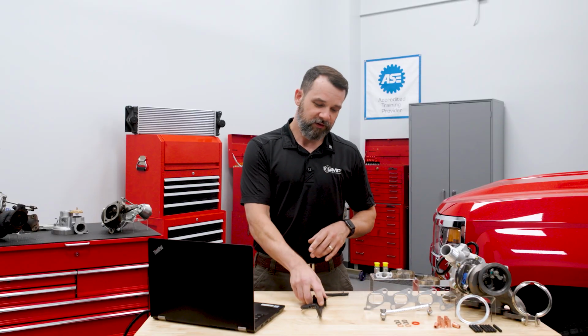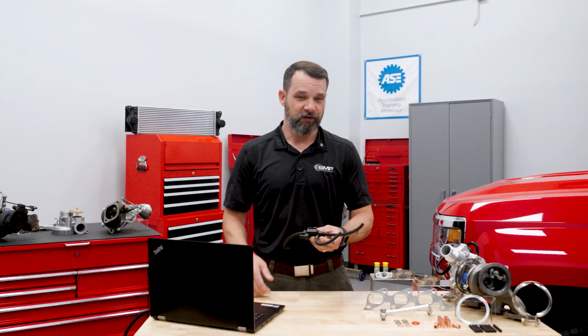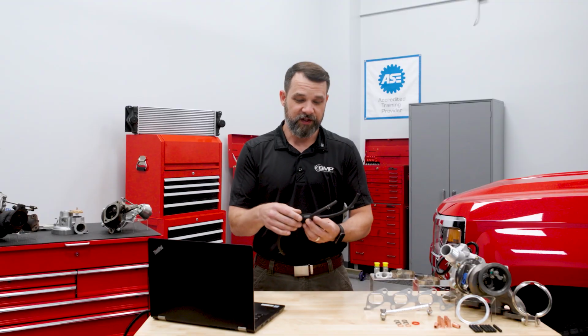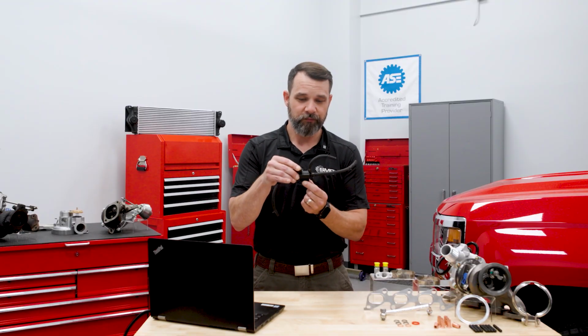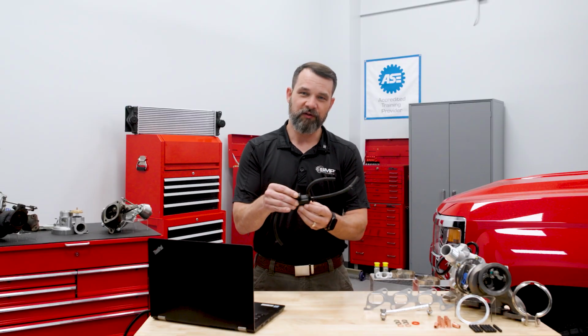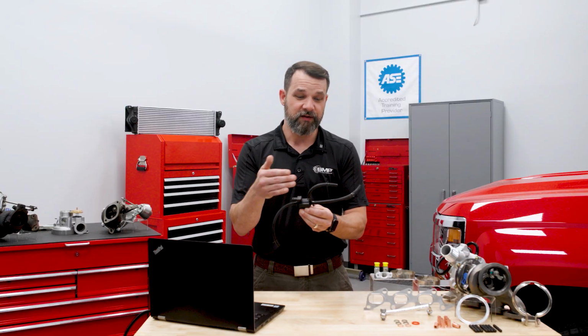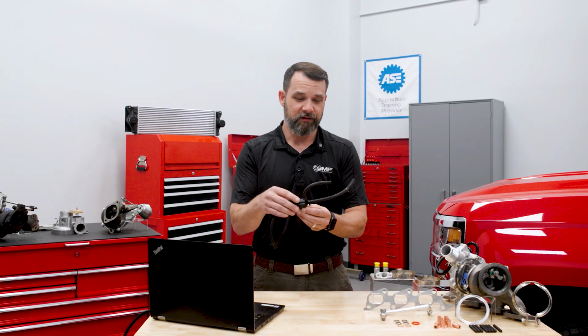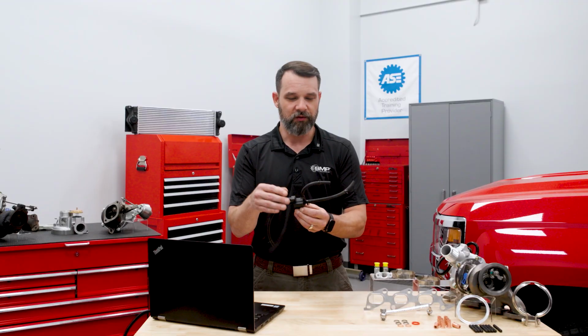Well, this solenoid for the turbo on the Escape, it really just sits. It slides in this groove down on a little arm that's on the turbo itself, and then it plugs in. So theoretically it shouldn't go anywhere, and in this case it didn't, which is nice. It can slip off, so that's one thing to look at.